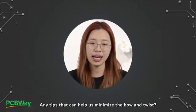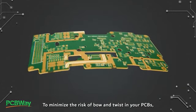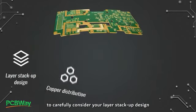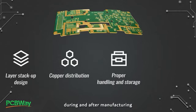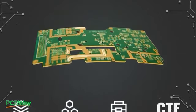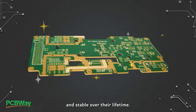Any tips that can help us minimize the bow and twist? To minimize the risk of bow and twist in your PCBs, it's important to carefully consider your layer stackup design and copper distribution. Proper handling and storage during and after manufacturing can also help prevent bow and twist. Additionally, using a suitable PCB material with a lower coefficient of thermal expansion can help minimize the effects of thermal stress on the board. By taking these steps, you can help ensure your PCBs remain flat and stable over their lifetime.